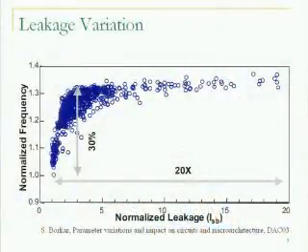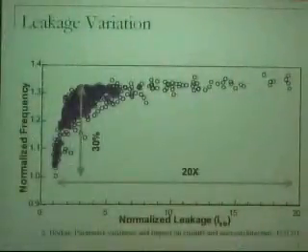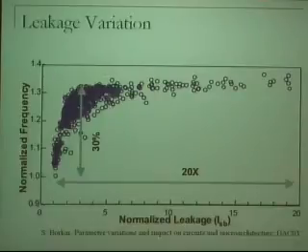So you see static power would be even increasing with temperature. The other bad news is leakage variation. You can see lots of similar results from Intel, IBM. There is a big difference in leakage for different chips at the same frequency. In other words, maybe the MP3 player that you get works for 20 hours, and the one that I get may work only for 5 hours, because the leakage is very high.